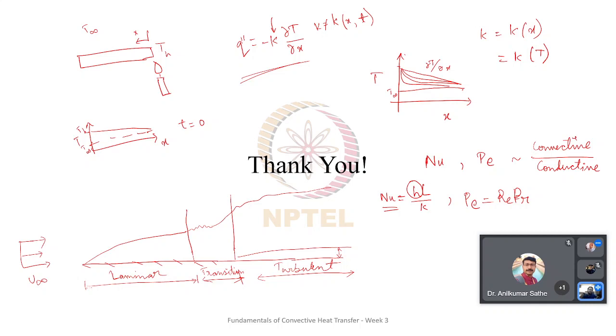So that comes from a different philosophy, that says that it's the ratio of the rates of advection and diffusion. So in a special case, in case of heat transfer, advection of heat is convection and diffusion of heat is conduction. So that's what Peclet number represents, or that's what its significance is.